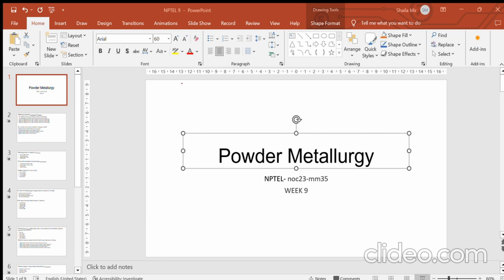But when you are going for pore rounding, where particles are being accumulated in these neck regions from some other region, it will result in pore rounding. So this is the right option for shrinkage. That means the shrinkage of the material takes place during pore rounding, which is an intermediate stage of your sintering process.